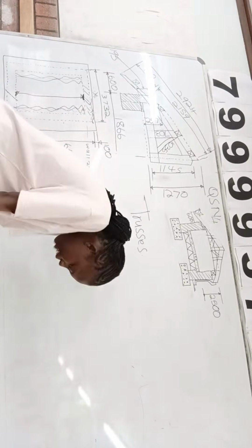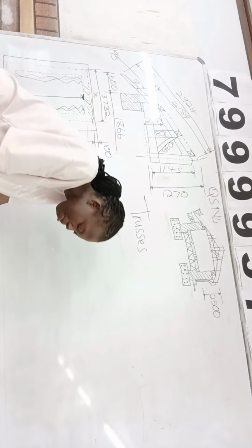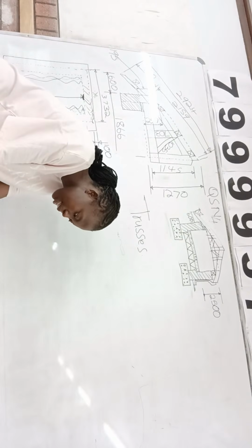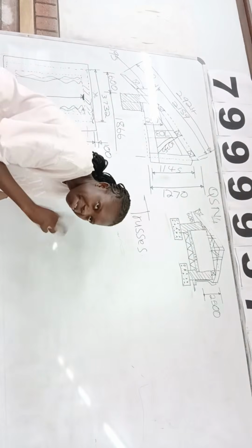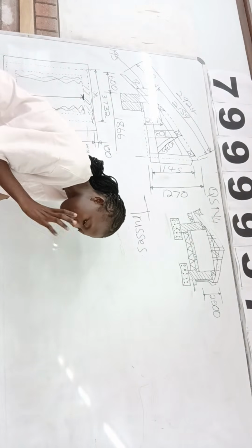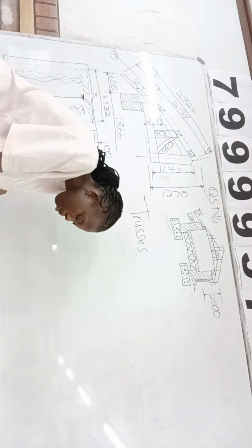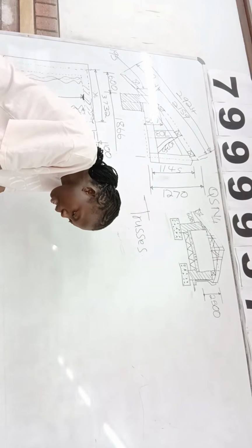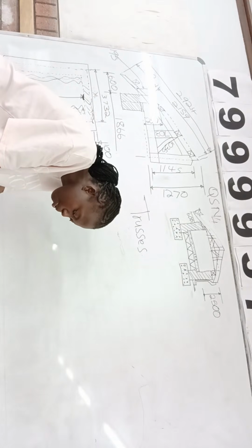Okay. Trusses. The construction of roof trusses varies. Some have members nailed together, others are bolted or gang nailed. This information is in N5 and 6. Again, some are nailed, some are bolted, some are gang nailed. So all the truss members are measured in meters to net length with no allowance for splay cuts, and the